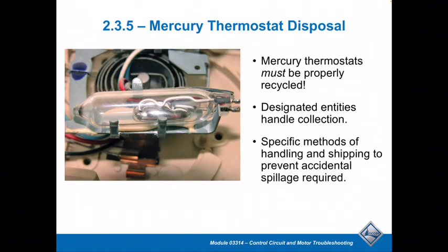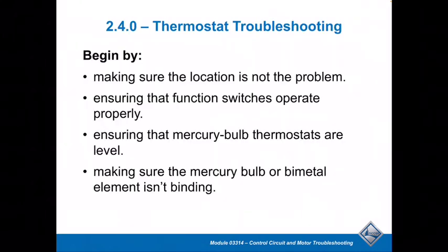So Mercury thermostats. As I had mentioned earlier, the Mercury thermostats are very hazardous. They're very dangerous. In the wrong hands, they create some serious health effects for people. So the Mercury thermostats, typically when you pull them out of jobs, you bring them back to the shop or you bring them to the wholesaler, and usually they'll have a recycling bin and they'll take them off your hands. But yeah, you do want to be pretty careful on those things. There's a lot of rules behind that.